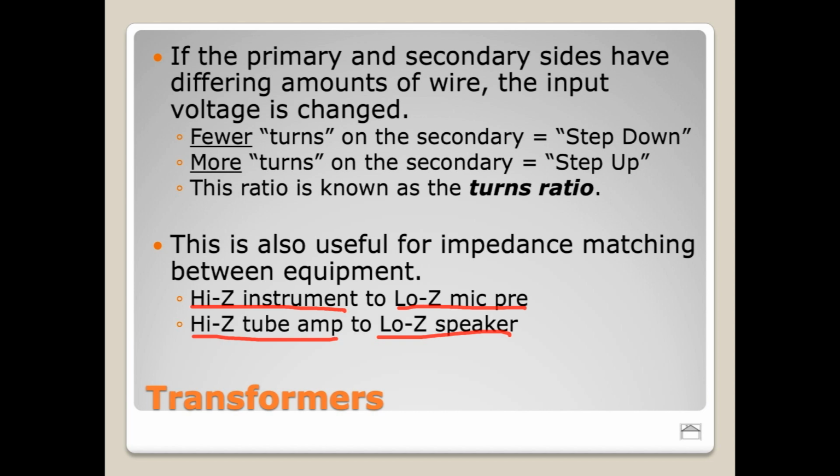These are your power amp tubes, and the output impedance on the power amp tubes is very, very high, but these are directly supposed to drive the loudspeakers, right? These are what actually push the energy to the loudspeakers and generate sound out of your amplifier.